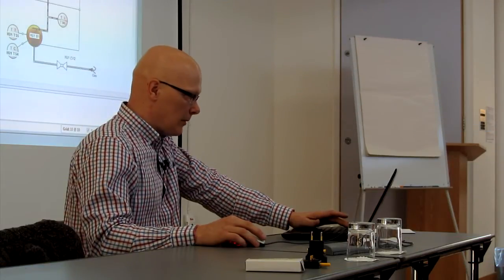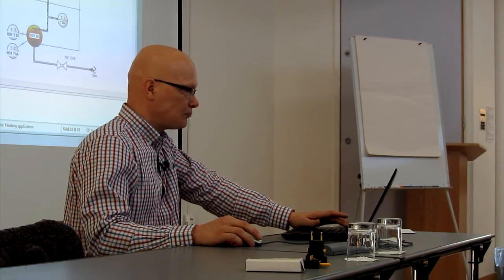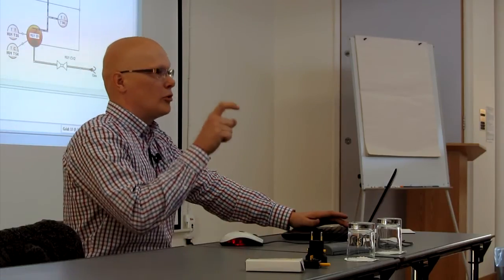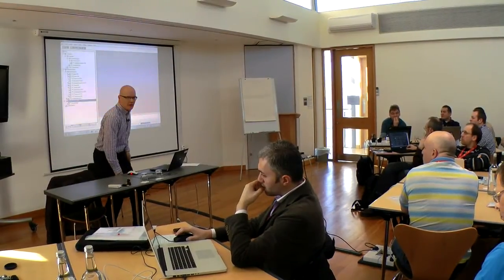But the last piece, of course, is that we want this to run somehow. So I have a code generator here that produces the exp files, which is the PLC code. But I also have TwinCAT here, which is an auto-build code generator. What this does is it produces the TwinCAT code, and TwinCAT is the tool by Beckhoff that allows you to run PLC capabilities on a PC. So this is the environment where the code is now being generated.